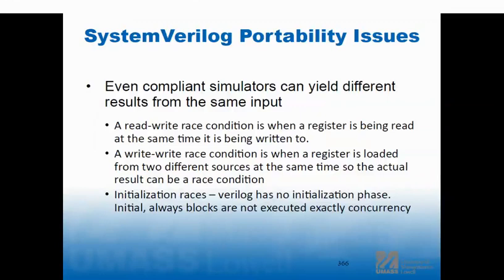Same with initialization. So what does this do? Sometimes simulators are very nice to you. So if you put a bunch of code into the simulator and you start running it, it works. But in reality, you can't rely on the fact that those flip-flops were zero. But the behavioral models all come up zero. And then you get into gate level simulations and, oh, wait a minute, this doesn't look the same in gate level as it did in behavioral, which is a good reason to run gate level simulations early in the process.